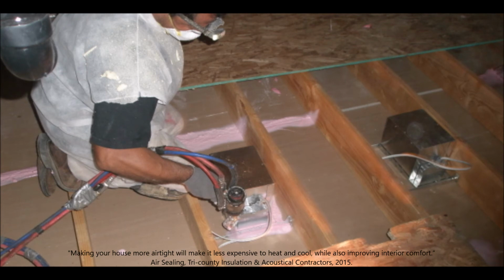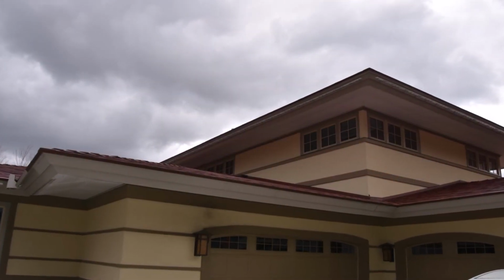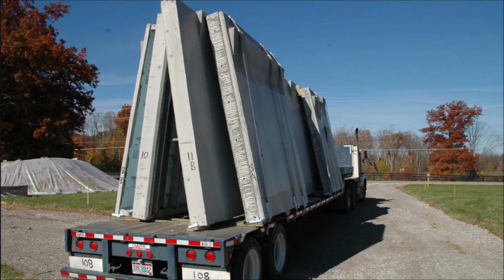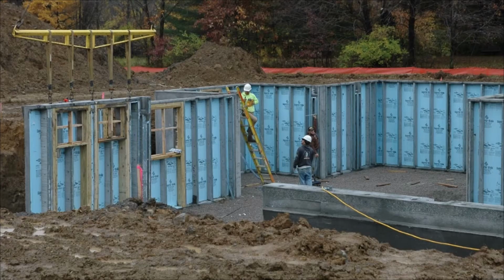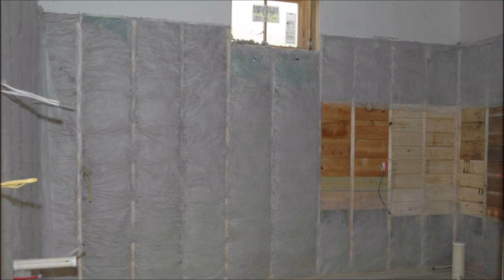Closed-cell foam was applied at the wall and ceiling intersections as well as around any penetration in the ceiling to reduce air leakage. The insulation continues into the large overhangs to go beyond the exterior walls of the home. The perimeter concrete walls in the basement are precast panels with blue board backing, making them impermeable to water penetration. This house has an additional 7.5 inches of insulation packed between the steel studs, increasing the basement's insulation value to a range of R33 to R47. This helps to reduce heat loss below grade.